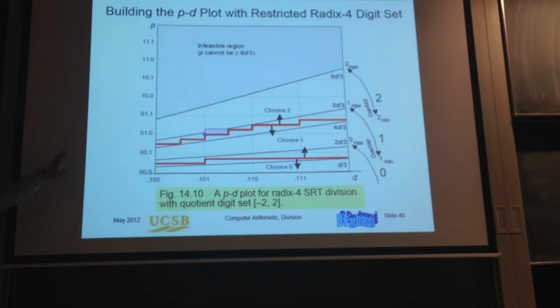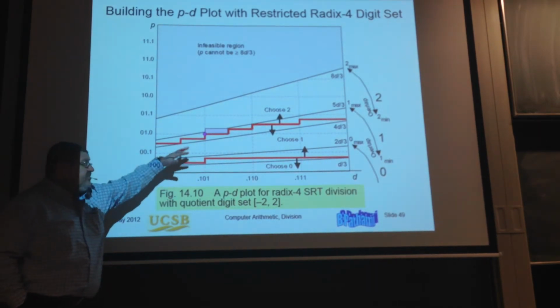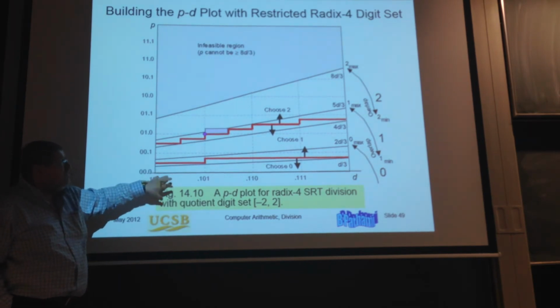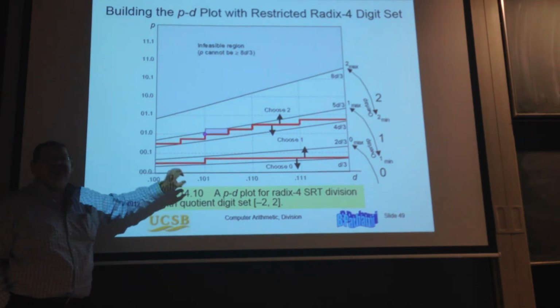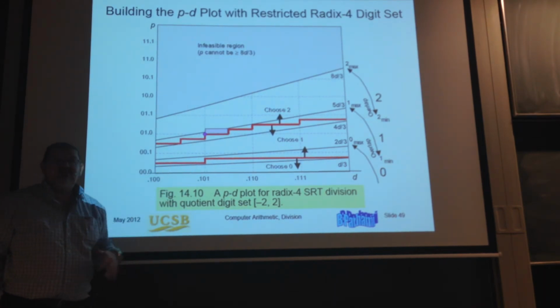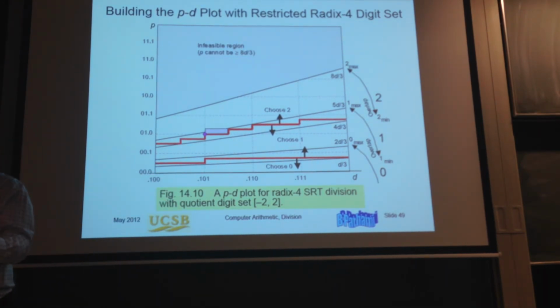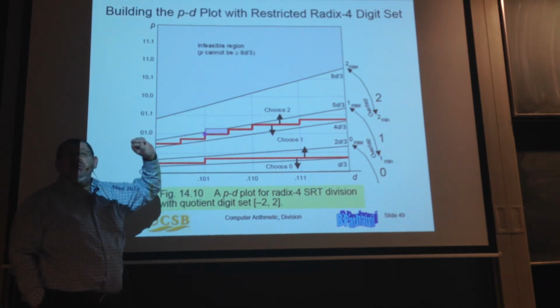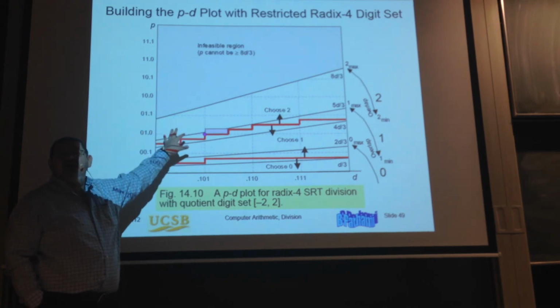And then determine the separation lines, see how many bits of P and how many bits of D I need to inspect, and then create the content of a lookup table where I should get the digits from. Then I address the lookup table with the proper bits of P and D, and then I get the choice.